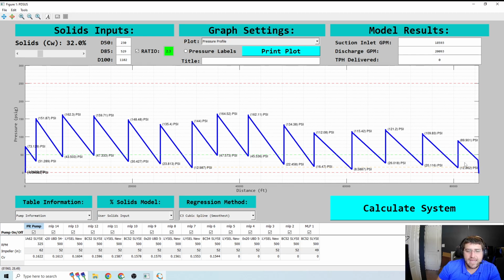Lastly, the static head consideration in this pipeline, we have a very large rise to the discharge. It's coming to the top of the plant. All that is no longer nice, heavy slurry. It is standard water. So all that back pressure we were getting is gone. And now we start seeing some very crazy trends going on, a lot closer to real process data existing here.